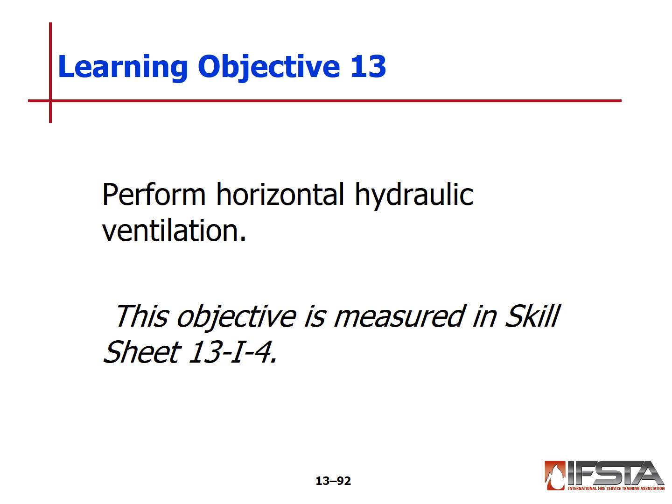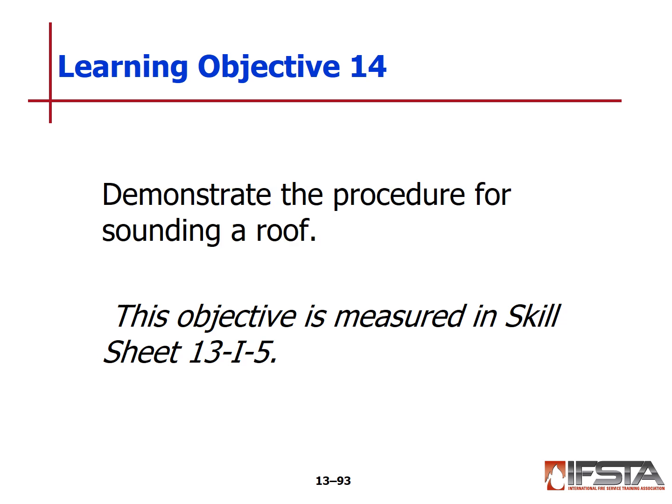Obviously, I told you we're going to go ahead and perform hydraulic ventilation. We'll do that in the trailer as well. Demonstrate the procedure for sounding a roof. You can do that just on the ground. Just take an axe and just every step you take, sound it out first.